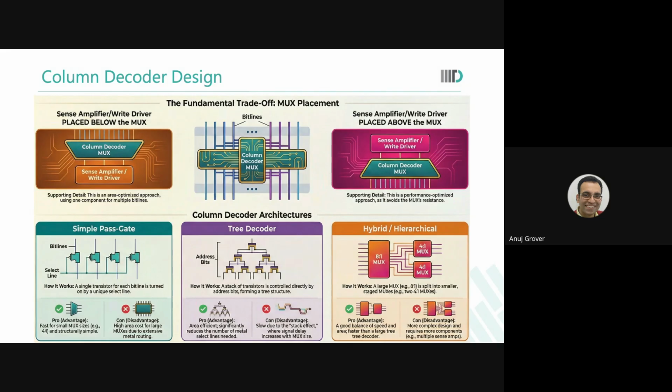A column decoding architecture doesn't become complex. Precharge architecture becomes complex. Where you would be sending the precharge clock to all the devices to turn them off, in a selective precharge case, you will also use the column decoding information in that precharge block. So the column decoding information does not just go into the column decoder part, it also goes into the precharge. That's how you have to redesign the interaction between column decoder and precharge blocks.